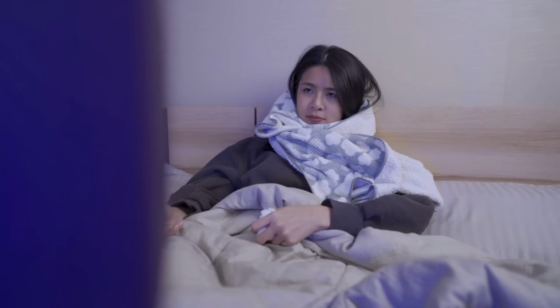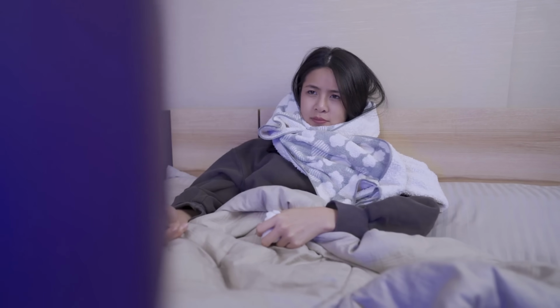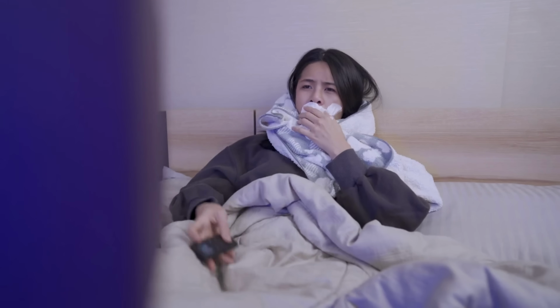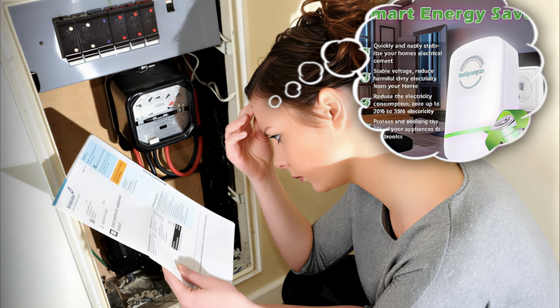If you have ever wondered why your heat feels dry or why one room is always colder than the others, it is because of a setting called cycles per hour, or CPH. Most contractors leave this at 5 for gas furnaces. That is a mistake that is costing you $50 a month.